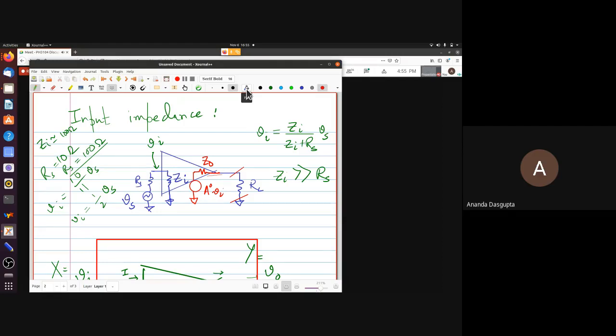You could change your RL. The RL is outside your amplifier, right? Depends, maybe it's a speaker. So it depends on which speaker you're using. Change your speaker, RL will change. If ZO is much smaller than whatever RL you have, it doesn't matter how big RL is. Whatever RL is, the entire AOVI is going to fall across RL. So it's not being large which is important, it's being independent of what RL is.